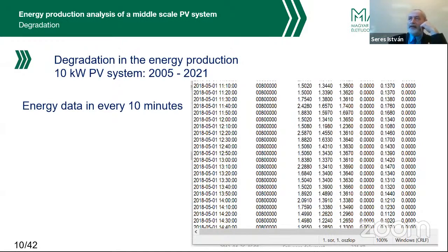On that side, we are measuring the AC side as well, how much energy was fed into the electric grid. We use a three-phase system, so the three different subsystems go to the three different phases. In this way, we can measure separately how much energy was taken to the grid during those 10 minutes. From these data, we can calculate the 10-minute average power for each subsystem.